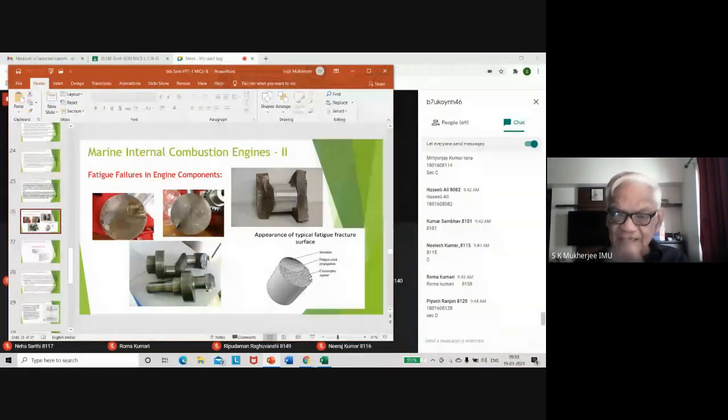And if you delay that by 2 or 3 days, it will become rusted and it will not look new anymore. But the fractured part, the crack region, will look old because it has been open to the atmosphere. It has partly oxidized, so it looks old, showing that the breakage has been old. But the lower part, what you see, will look fresh. Of course, if you detect it immediately. If you detect it after 10 days, that side will also look old. But immediate detection will show that this part is shiny, nascent metal exposed. Okay, so this is how it happens.